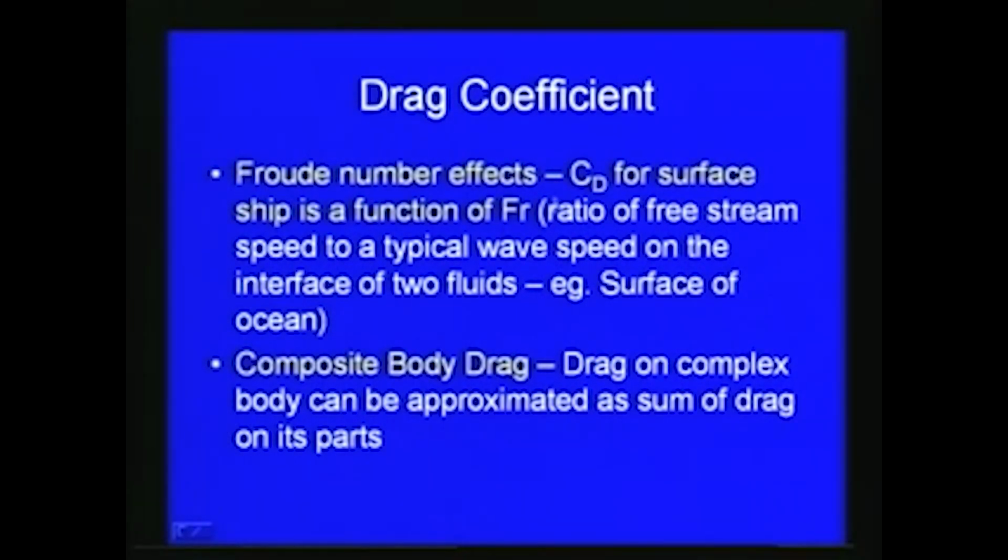Then we can show that depending upon the Froude number, the coefficient of drag changes. Whether this depends upon various other parameters of the wave effects, we can show that Froude number also has an effect as far as drag coefficient or drag force is concerned.